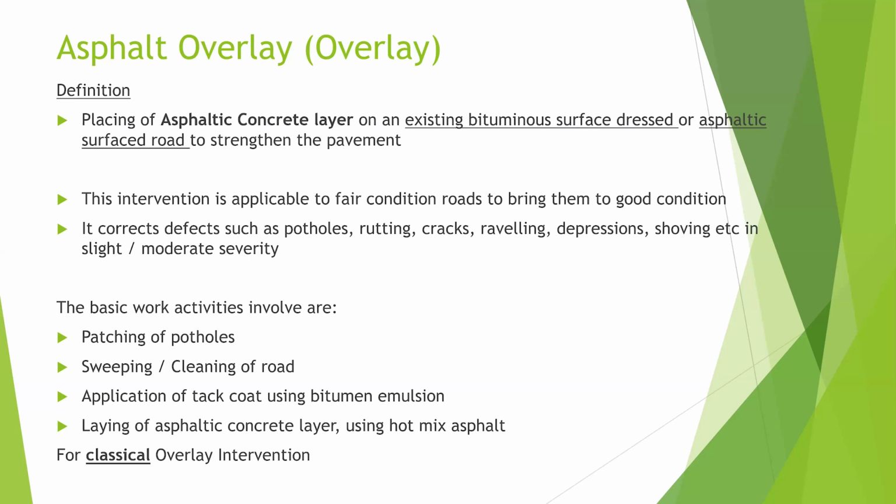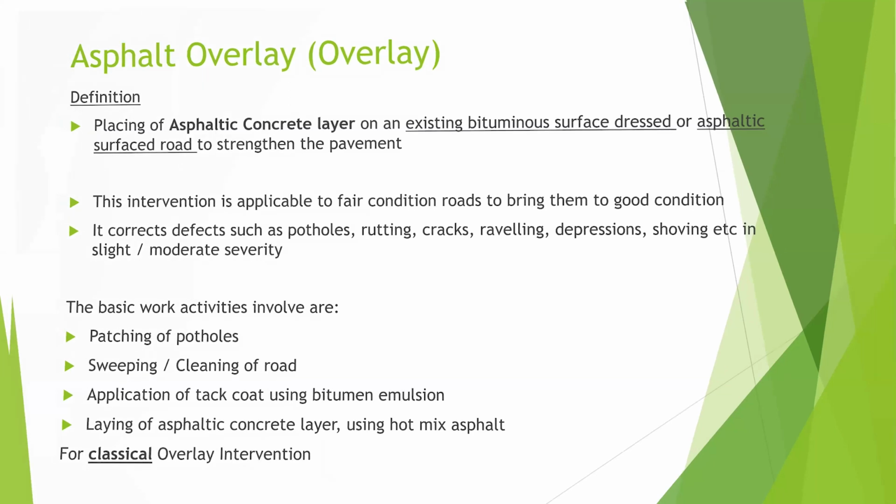Now, the basic work activities involved here are the patching of potholes. Few potholes that are on the road, you need to patch them. You sweep or clean the road to make sure it's free from all unwanted materials on the road. And then you apply your tar coats using bitumen emulsion, and then you lay your asphalt concrete using a hot mix. And so this is the classical overlay intervention.